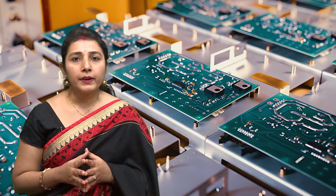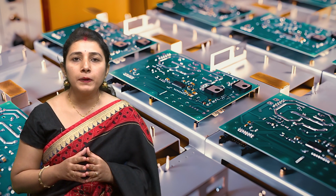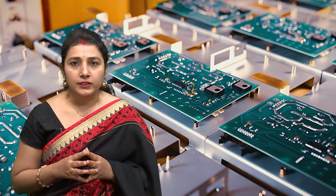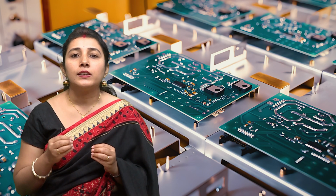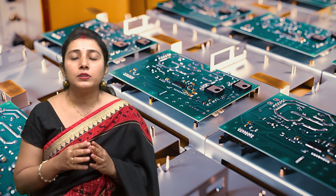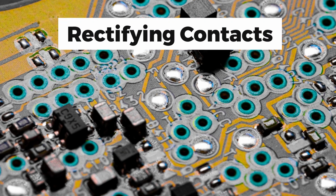A practical method for forming an ohmic contact is by doping the semiconductor heavily in the contact region. Thus, if a barrier exists at the interface, the depletion region width is small enough to allow the carriers to tunnel through the barrier. Now comes rectifying contacts.